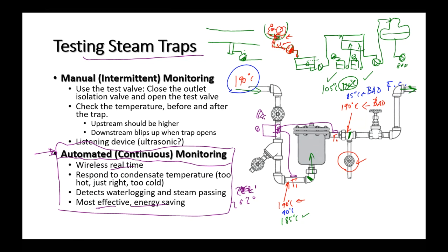So what we end up with is steam in the vessel, steam in the inlet piping to the trap, and steam inside the body of the trap, until it radiates enough heat that it condenses. And of course, as it condenses, it will flow into the trap and cause the trap to operate again. Does that better answer your question? Yeah.